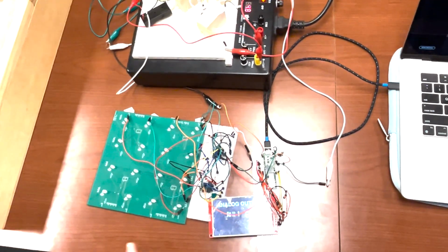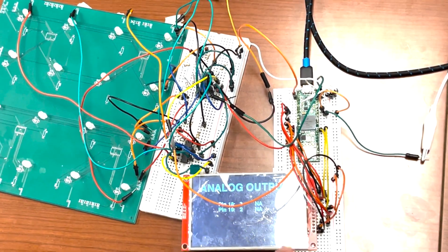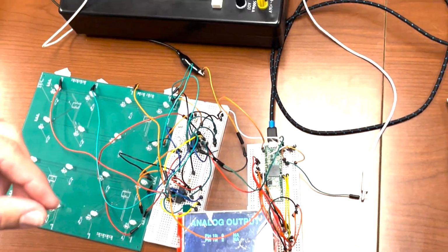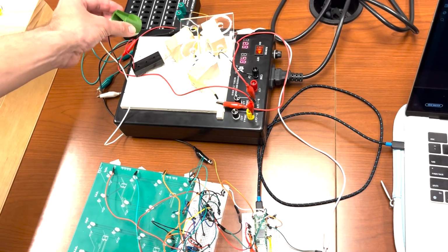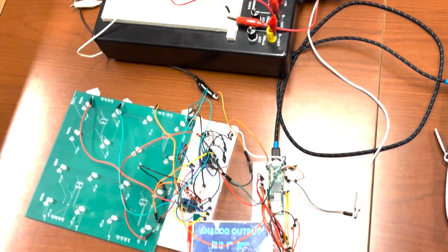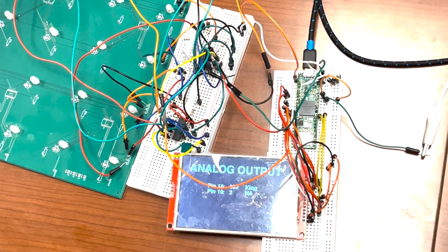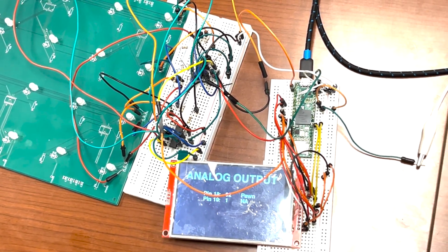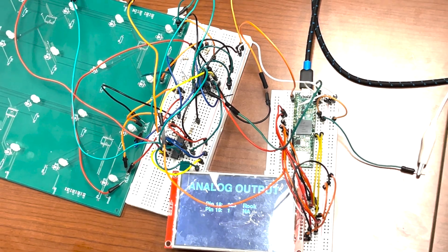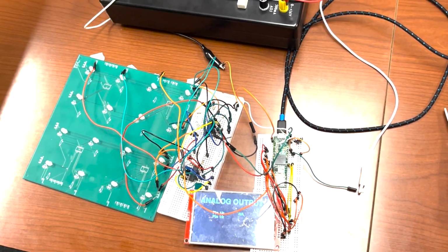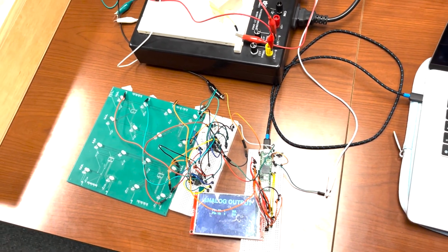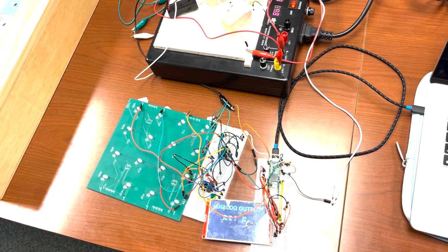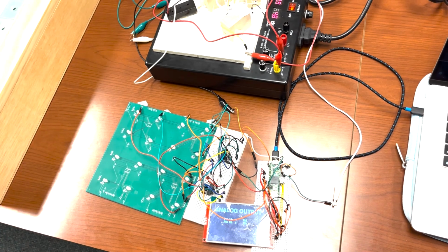So here, from 0 to about 70, we have it set to not available, or an empty piece, no piece available on the board. And now we can take the base here, place it directly on top, and receive the value for a king. As I lift it up as well, you can see that it ranges some different values since it's reading all of it immediately, but using a calibration system where it waits to read a stable value, it will then read the exact piece, preventing a player from making it change rapidly as you're lifting it up and down.